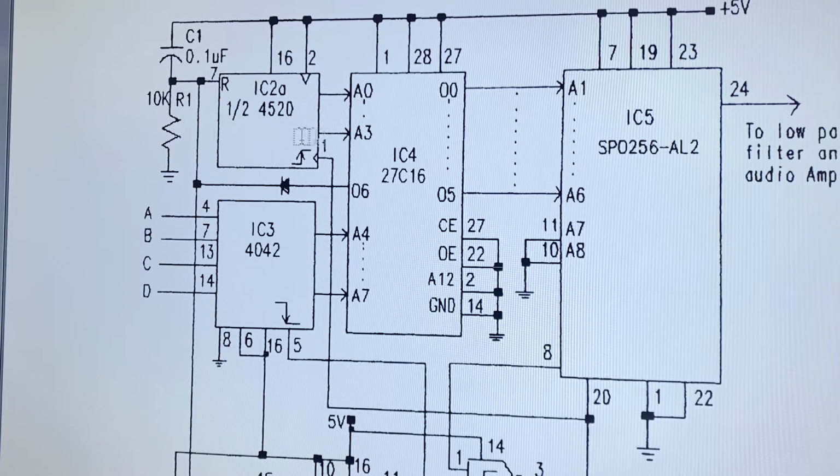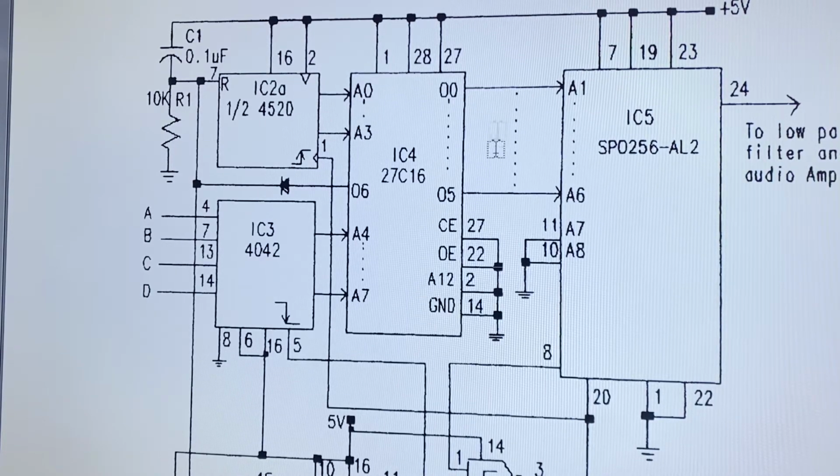So when you want to read the data in a memory, you have to scan it in the lower bits, in this case A0 through A3, which is 4 bits, so you can scan up to 16 bytes of memory. The data is given in this data bus from output 0 through output 5, because output 6 and 7 are used for other purposes.